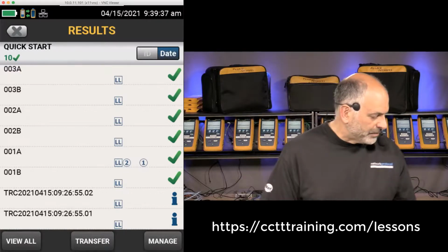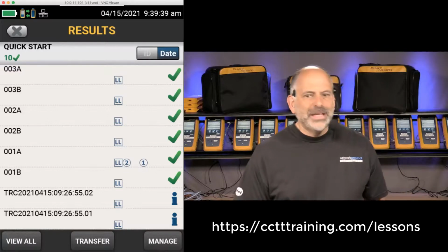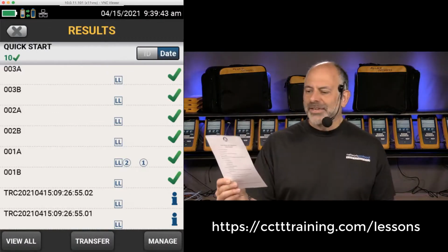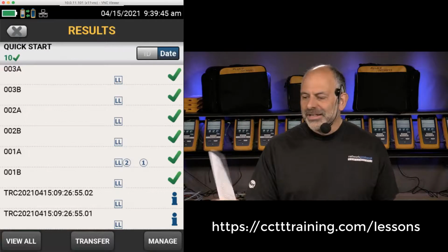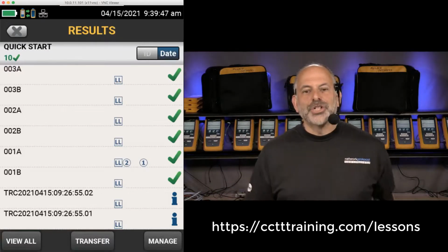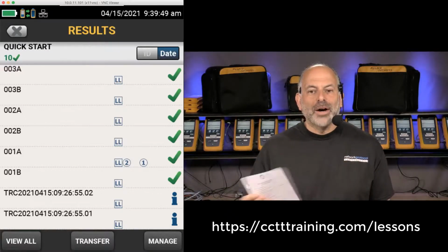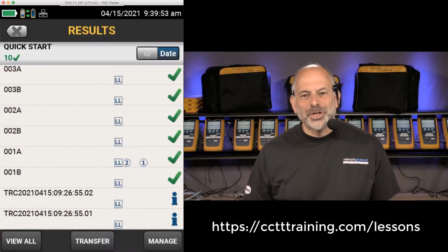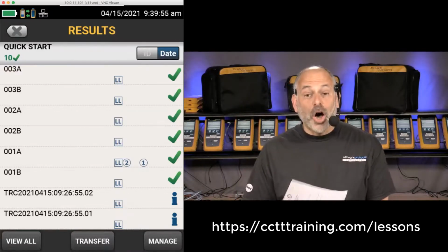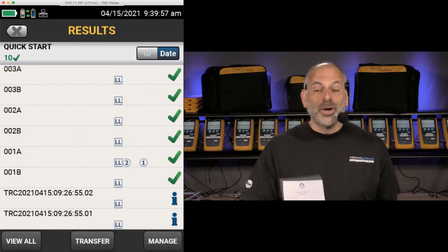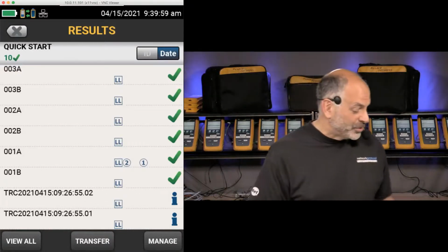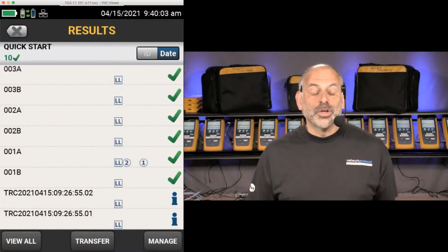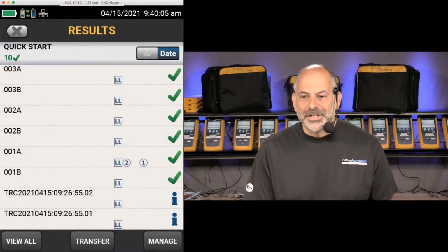I'll tell you what, I'm going to send a follow-up email to everyone. And one of the things that we'll have a link to in there is I put together just a little PDF that's got some testing checklists. So when you're going to go out and do testing, these are the steps that you want to make sure you follow. And on there for the CertiFiber Pro, we have the values for each of our different fiber types of what values we're looking for when we set reference.